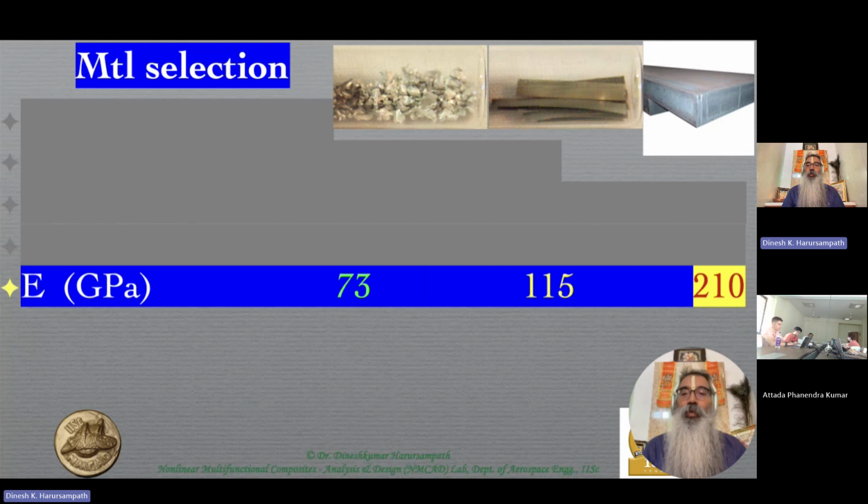Again, you see a very similar gradation as we saw in the case of sigma U. As far as aluminum is concerned, there's a typical ballpark value, and here there's not as much of a spread in the range of values. Sigma U values can vary quite a bit between specific choices of aluminum alloys, but E, the Young's modulus, doesn't vary as much.